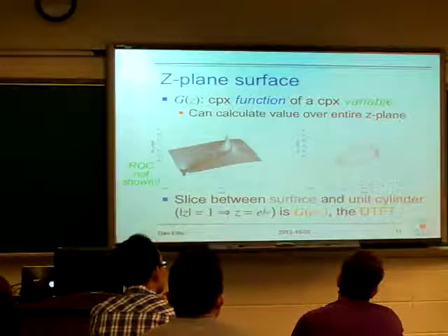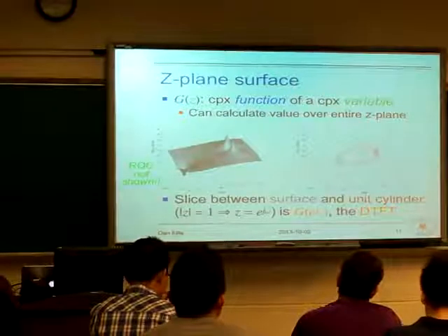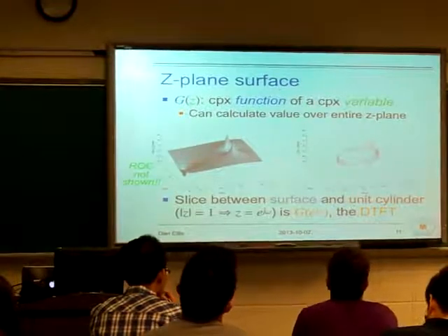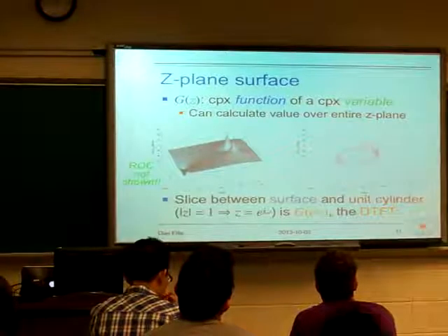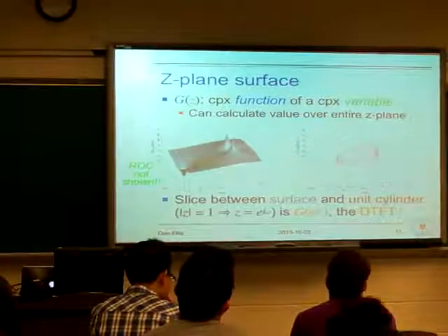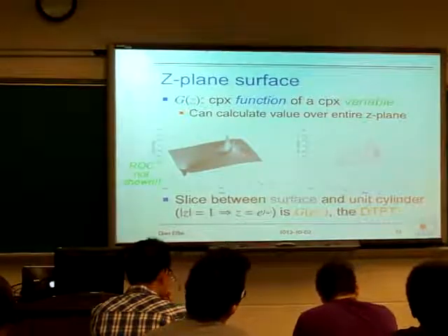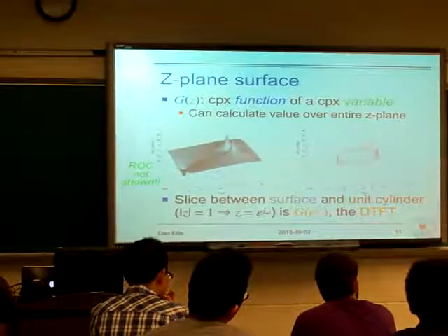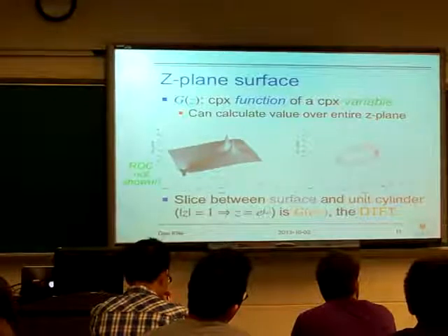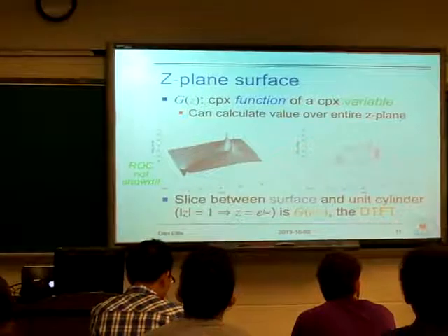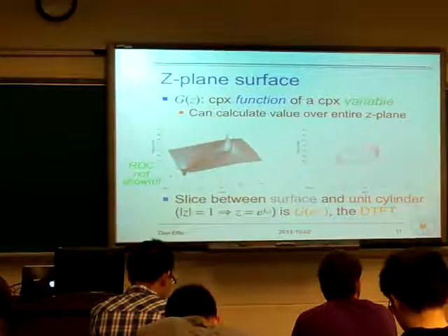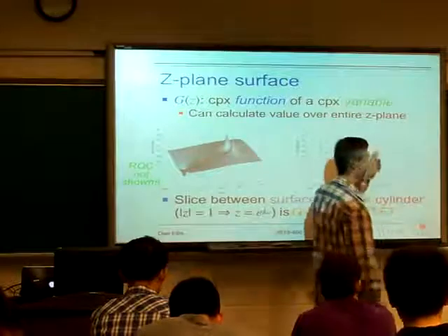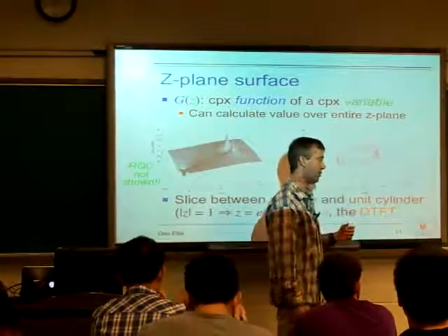So that's what we're saying, that by evaluating the Z transform for this particular set of values of z, which is the unit circle, right? Because this thing has a magnitude of 1 and an angle of omega. This is a function over all possible values of a complex variable, so it's all possible values on a Cartesian plane. But there's a one-dimensional subset, a circle in this case, and when we evaluate those, we just get this thing. And of course, it even works algebraically, because this expression had e to the j omega where we put the z. If we just think of z being this constrained set of values e to the j omega, this is what we get.